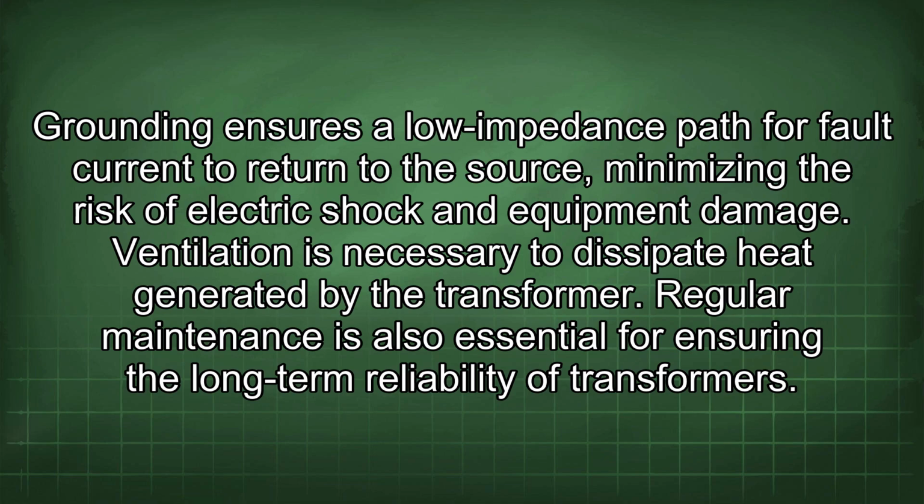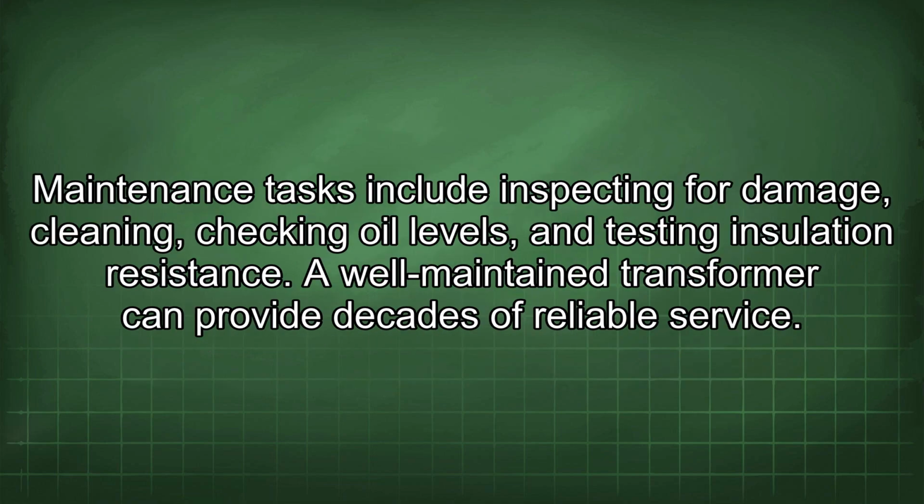Regular maintenance is also essential for ensuring the long-term reliability of transformers. Maintenance tasks include inspecting for damage, cleaning, checking oil levels, and testing insulation resistance. A well-maintained transformer can provide decades of reliable service.